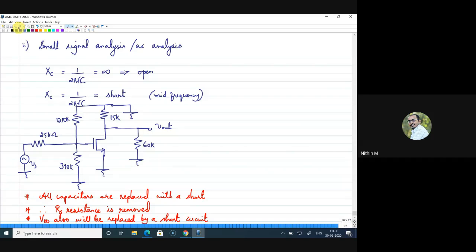So with this, now if I want to analyze the small signal equivalent circuit, I should replace the MOSFET with its equivalent. Right. So what is the MOSFET's equivalent? Let me draw the three terminals here, 1, 2, 3. Since it is a MOSFET, I will use a different color just to identify between the components. So this is your gate, this is drain, and this is source.